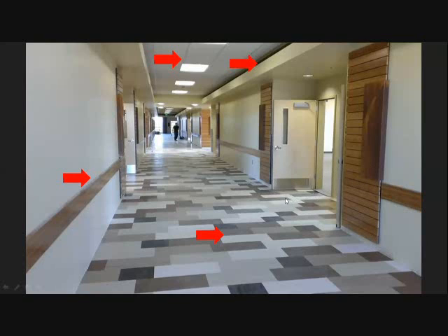As you see here, we also provide a small space for the doors to open so that if someone is going back and forth with a trolley or something, they don't get hit by a door opening. So we have to make sure that we create these small lobbies in front of the rooms for the doors to open.